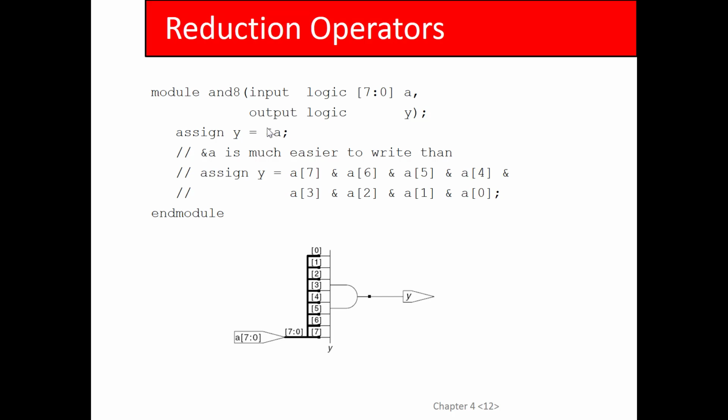But the other difference, too, is that in Verilog, indices generally start at 0, right? So if I want 8 bits, I've got to go 7:0, giving me bit 7, which is my most significant bit, and 0, my least significant bit. Everyone, that make sense? So use square brackets when you address individual bits or ranges of bits, and also brackets when you declare a signal. Why can't I just say logic 8 A? I don't know why they don't. They make you do 7:0, which means 7 down to 0.